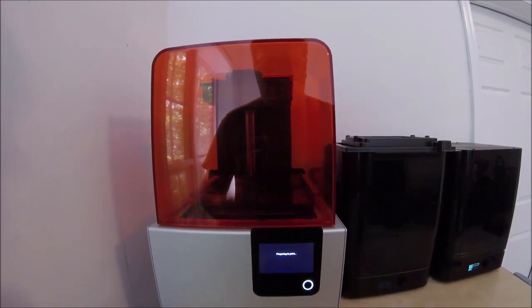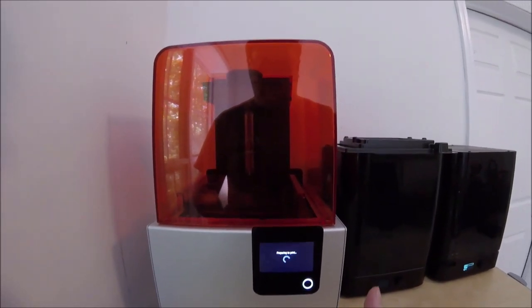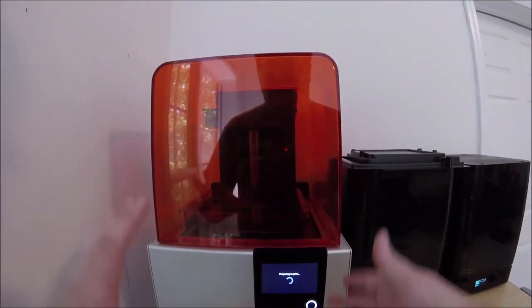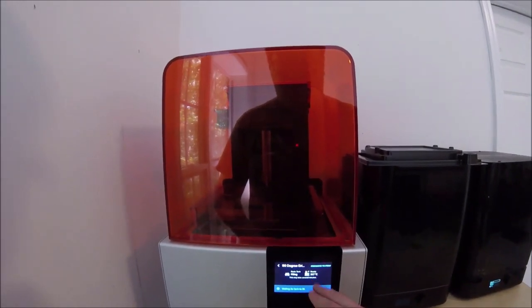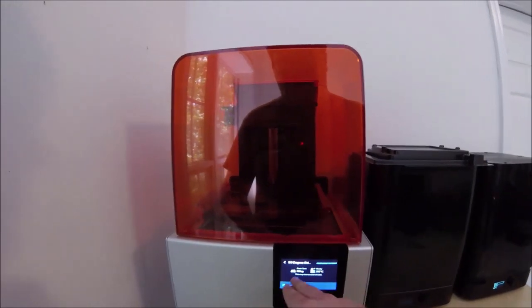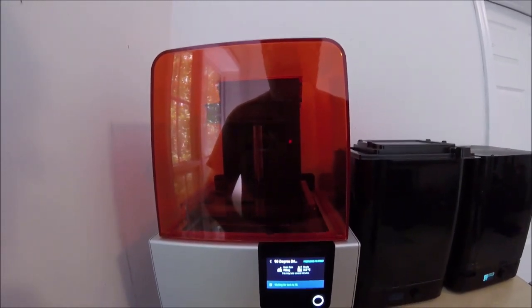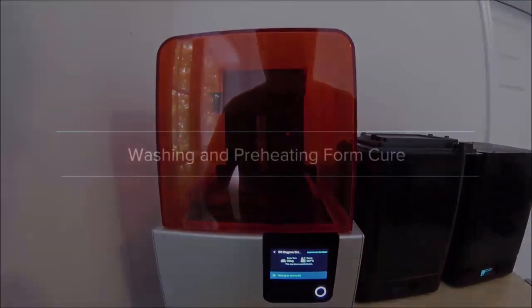Now the printer is going to go through a couple steps and initialize. It's also going to heat the resin up to about 35 degrees Celsius before it starts printing. So you'll see it says preparing to print. It's going to do a couple motor moves, and then the screen will come up saying we're at about 31.7 degrees Celsius. So it's going to heat up from there to 35. It's also filling the resin tank and ensuring that the level of resin in the resin tank is appropriate. So once it finishes all of these steps, it'll begin the print job.